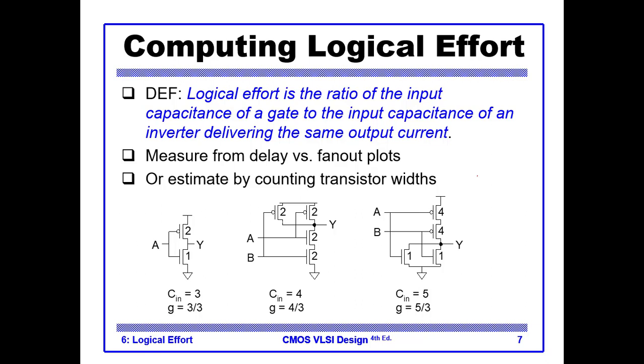So let's come first to the definition of logical effort. The logical effort is the ratio of input capacitance of a gate to the input capacitance of an inverter delivering the same output current. So let's understand this with examples.